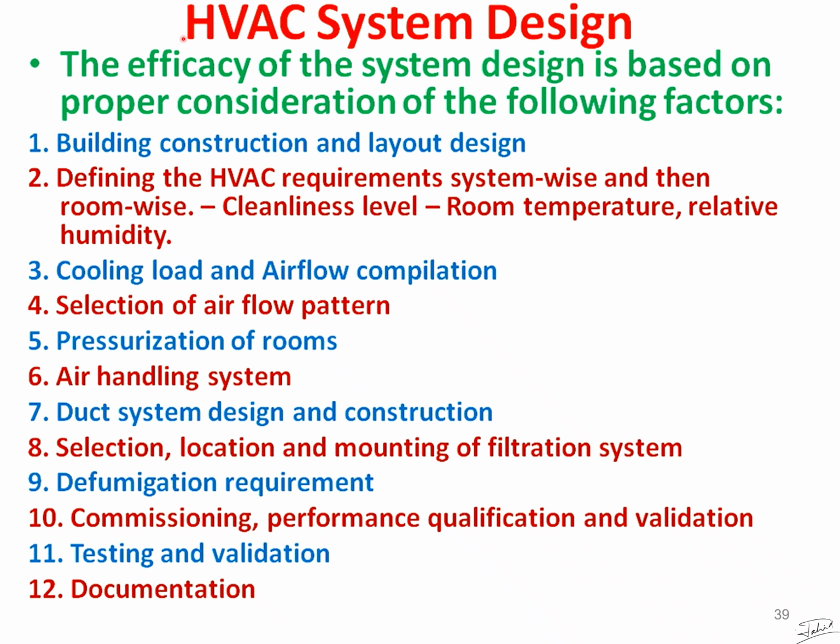So we can see here, if you want to build a new pharma company, then how would you design your HVAC system? Okay, so this is the step-by-step procedure. First of all, you have to have a layout design and building construction, where you will place your manufacturing area and where you will place your HVAC system, because not every unit requires this HVAC system. For example, the warehouse area doesn't need this HVAC system. A pharmaceutical manufacturing site also has an engineering department, which doesn't require an HVAC system.